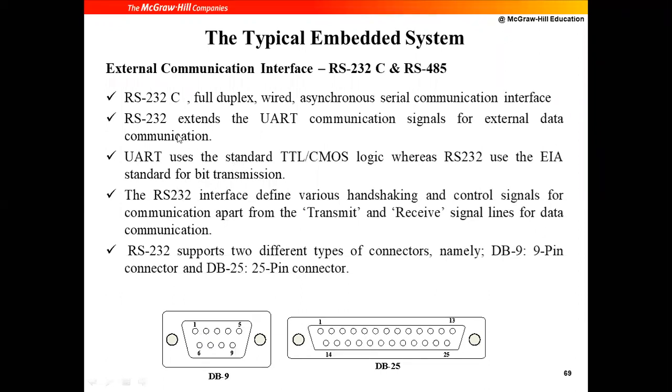So basically this RS-232 is nothing but the extension of UART communication. In the previous class, we have seen UART, universal asynchronous receiver and transmitter, right? It is an extension of this. Along with the two pins, that is transmission and receiving pin, we have various acknowledgement signals. Okay, we have TX as well as RX pin over here. Along with that, there are various control signals or acknowledgement signals generated in this RS-232 cable.